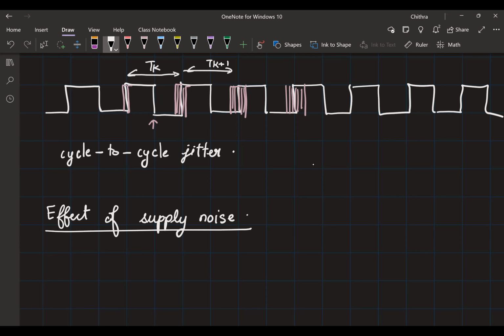I mean, it is going to deviate a lot from the expected clock, right? So as with most of the problems we deal with in analog circuits, there would be some solution, and usually the solution is to put everything in a negative feedback. So it turns out you can design an oscillator and put that in a negative feedback, and then you can sort of bound the jitter of the oscillator. Putting this oscillator in a negative feedback results in a phase lock loop circuit.